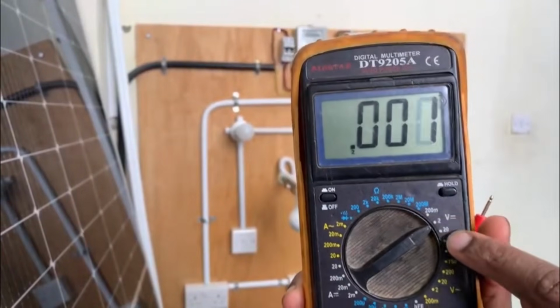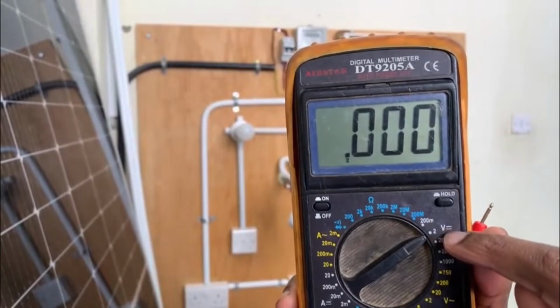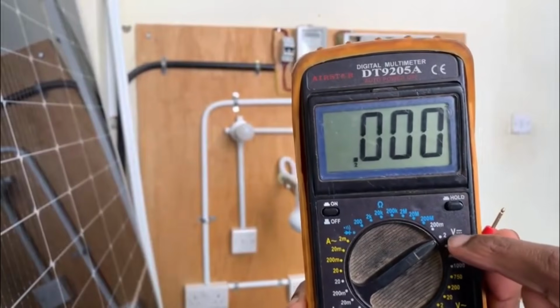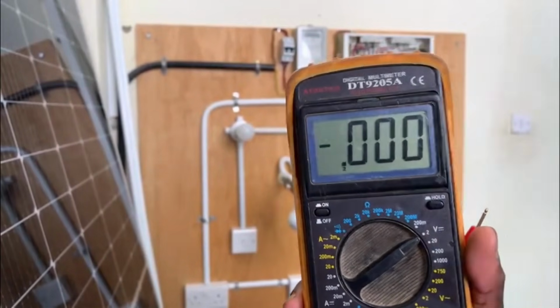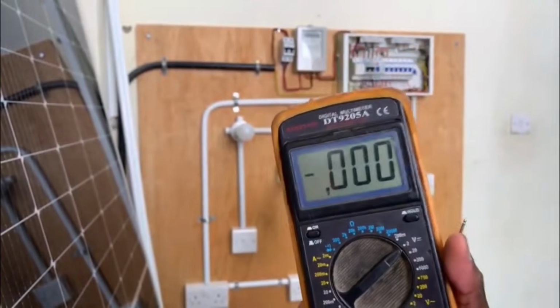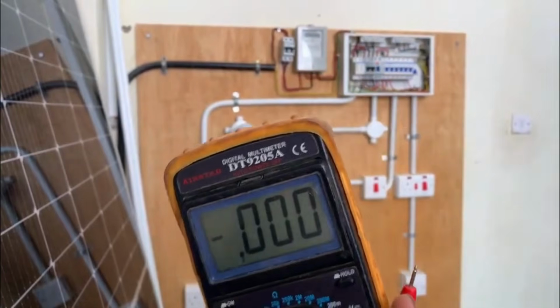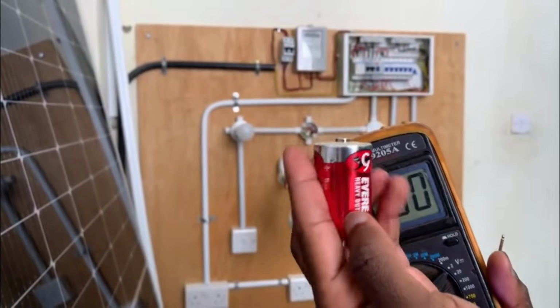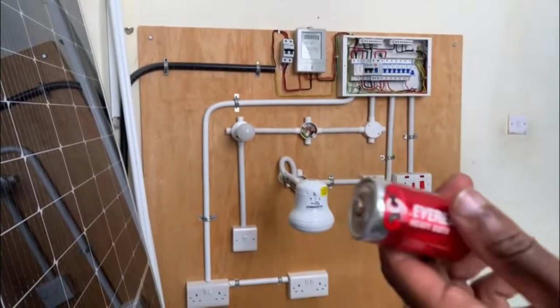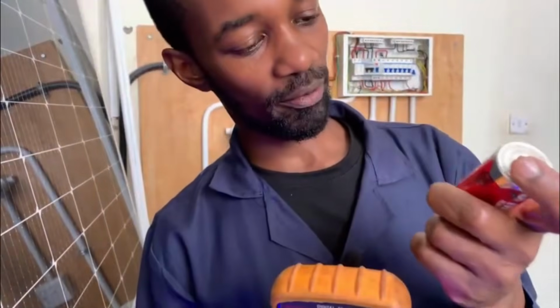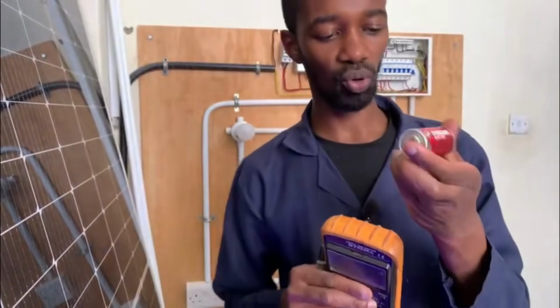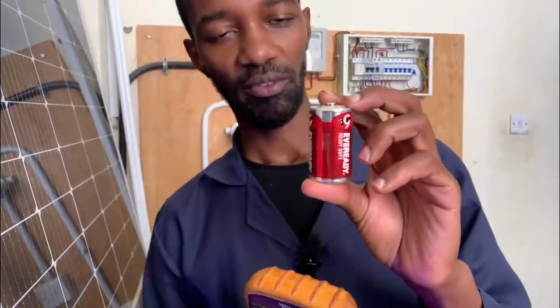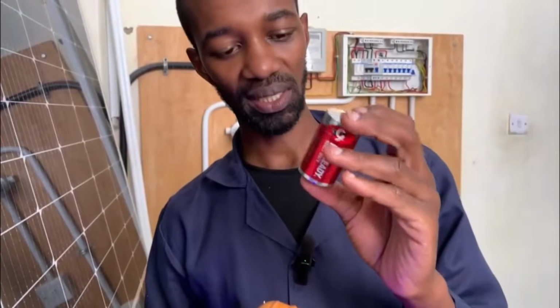Now, when it comes to direct current voltage, DC, you place it here. All this white that you can see here, the V, the line and the dots, is direct current or direct voltage, DC. So you place it here, assuming that we want to take the readings of the voltage of this battery. Is it a battery or is it a cell? Everready is such a great product. So, when it comes to taking readings from a digital multimeter, you really need to understand what you are expecting or what you are recording.